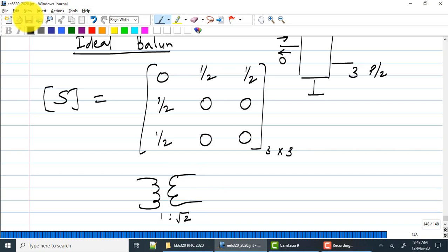You have a similar behavioral description for analog circuits that is called Verilog A. This description is written in Verilog A in the AHDL lib. It's a behavioral balun. It works with your Cadence simulator. If you are using Eldo, there must be a similar kind of balun. If not, just build your own balun or use a transformer. No problem.